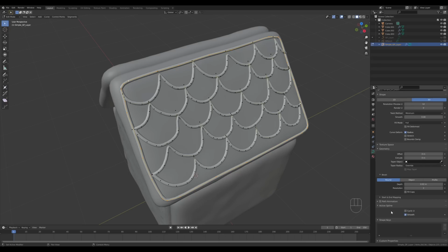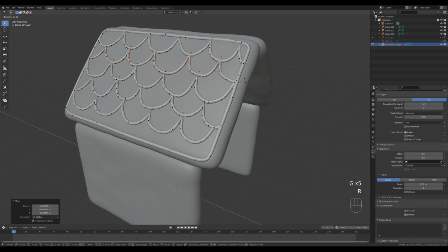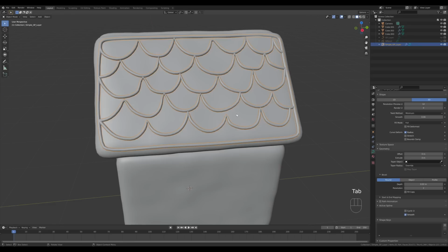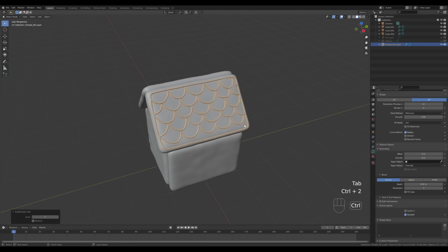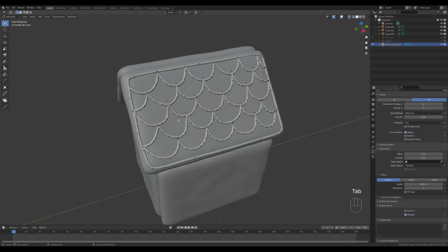Let's go to the active spline settings and enable cyclic. That will close it up and you can adjust the corner. And again, move some of these points around so you don't have these weird overlaps or unfinished curves. Okay, let's tab out, and optionally I will increase that resolution. So this is a little bit tedious way how to do this, but for the high definition illustration purposes, I think it's worth it. You will get really nice definition and smoothness to this.